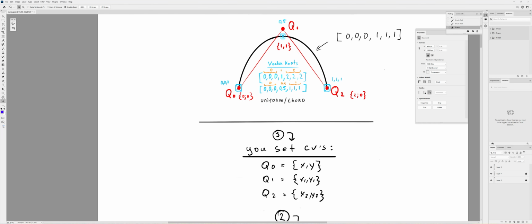Now, with uniform, we are talking specifically and only about internal parameterization. We are not talking about any actual distances. We are not tied to coordinates on anything. It just uniformly increases 0, 1, 2, 3, 4, 5, 6, 7. It is within the parametric space of your domain. The chord, instead, is actually constructed.